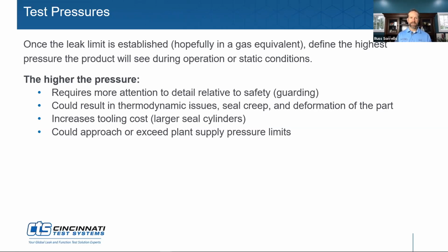One of the ways I like to explain those thermodynamic issues as it relates to test pressure is that we've got about this much volume of air, and then we're going to open the part in our test circuit up to that air. So it's going to expand, and then it's going to compress again. And that is where those thermodynamic issues come in. We've expanded, now we're contracting, and of course that event creates thermal energy.